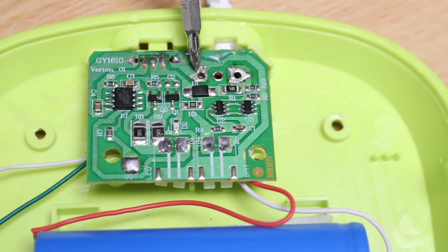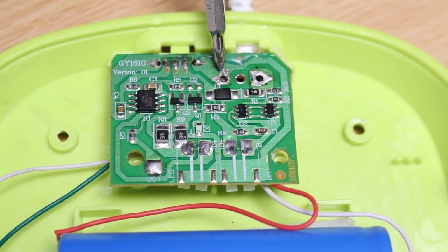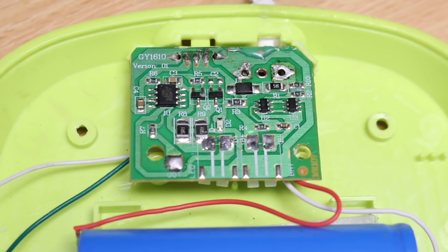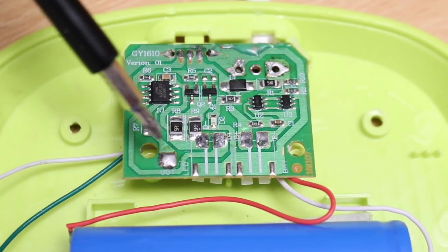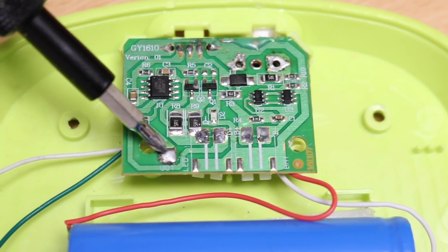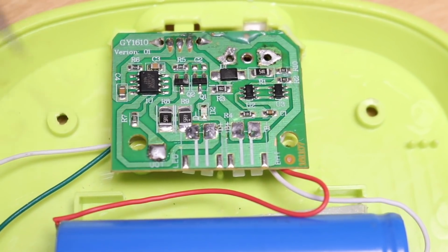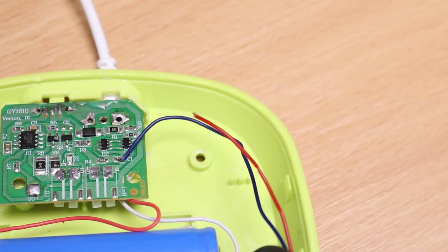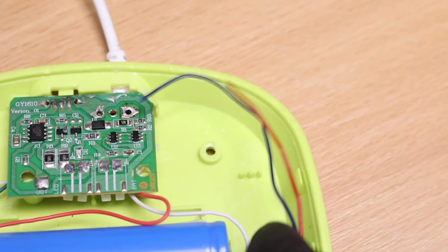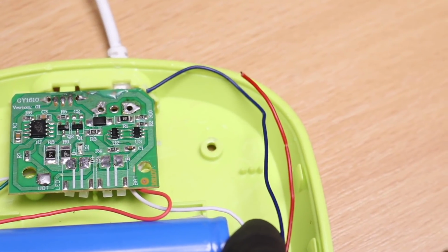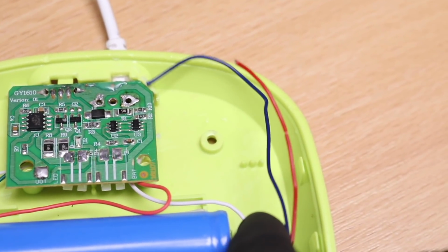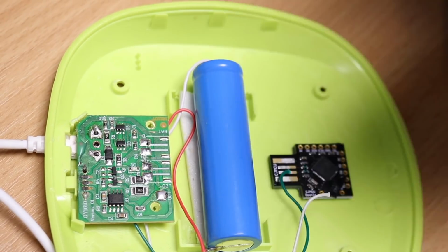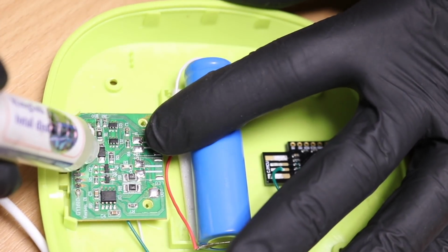Okay, so I'm going to resolder these two main points here. These power the board, and we're also going to attach power for our Arduino. And on the final assembly stage, I'm also going to resolder the switch, which was connected here. The two wires that I'm going to use are just generic small gauge wires that we're going to attach to the Arduino to power it. First of all, I'm going to connect my two power cables so that I can supply power to the Arduino board. Okay, so I'm going to apply a little bit of flux onto the points.